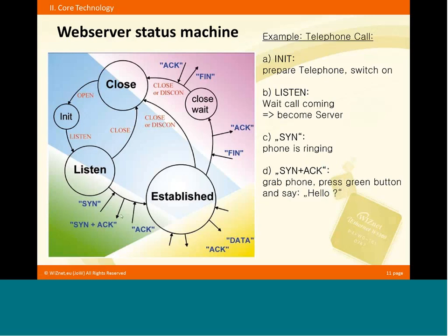That is like pressing the green button and saying, hello, I'm Joachim and I'd like to talk with you. This is completely automatically processed by the hardware TCP/IP engine. So the MCU does not even know about it. Then again, there is an acknowledge because you respond to me. Yes, I have time. I'd like to talk with you. Now, after these 3 packages going in and out automatically, the TCP/IP socket is going into the established mode.